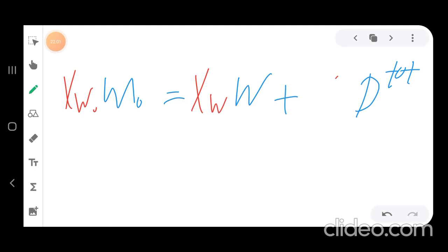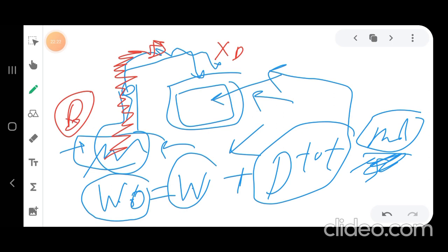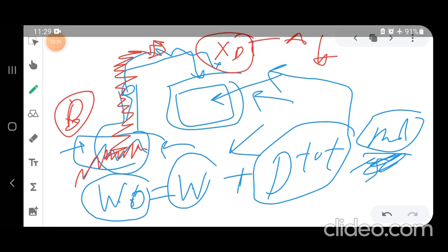But a very important problem that I would like to discuss is that this x D varies with time. As you vaporize, you will take more B with you, isn't it? B is heavy, but as you vaporize, you are giving more heat, so you are causing this heavy component to also be vaporized. So what will happen to this x D, which is the composition of A? It will decrease. So you don't have a constant x D in simple batch distillation.